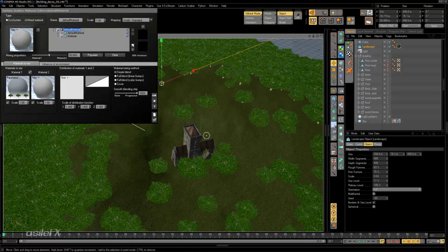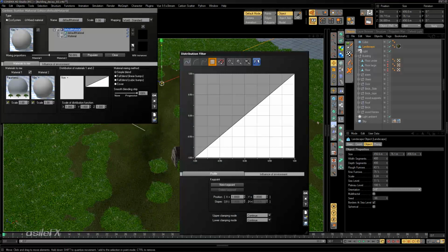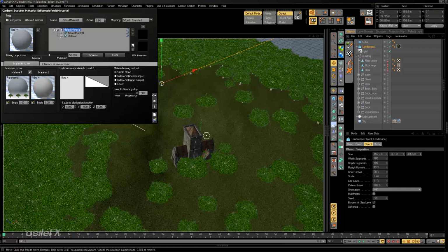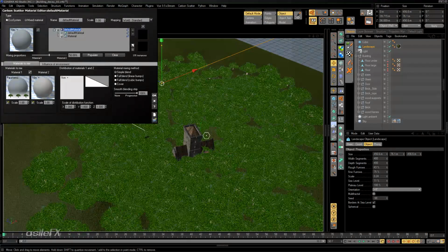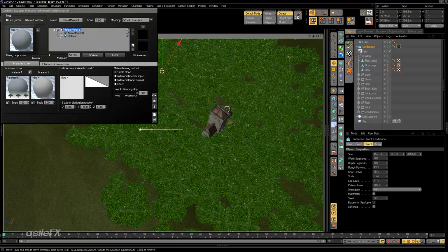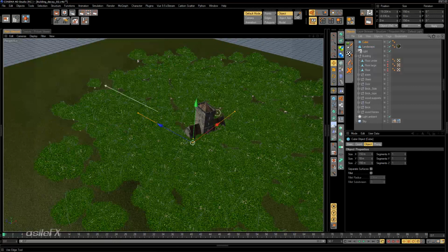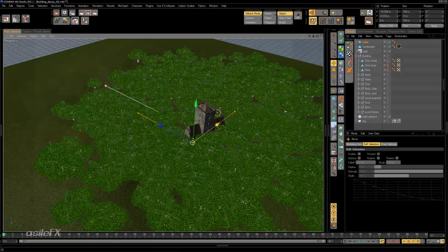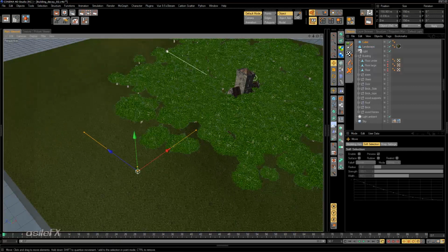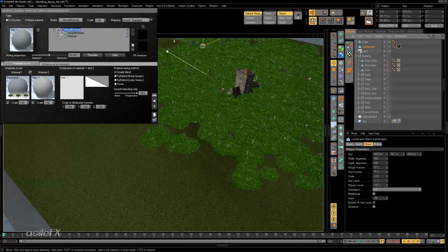So we can transition through it a bit further. Now if we want to reverse this, it's actually quite easy. We can edit the filter, and in the upper right we have a flip filter button. Click OK, populate, and now it's just going to populate within that noise. So that's pretty cool. We can go ahead and take the cube, switch to the object mode. I'm going to move it over to the side, and then go back into the landscape, populate the object,